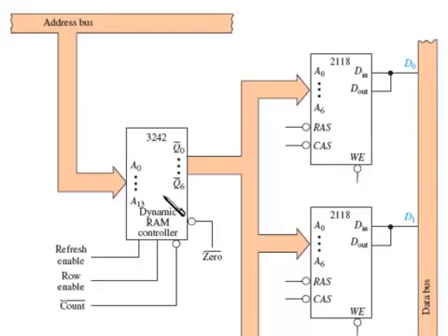This dynamic RAM also has a refresh enable, and when this is made high, the counter counts through all 128 columns in an entire chip, and it refreshes all the capacitors. Basically, it looks at each capacitor in the columns, and if any of them are high, it recharges them. And this runs at a speed dictated by the count frequency on the count line.